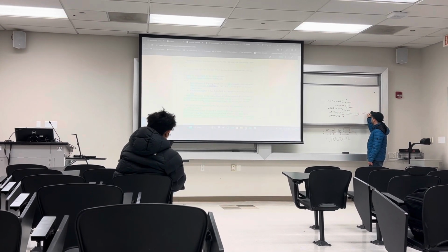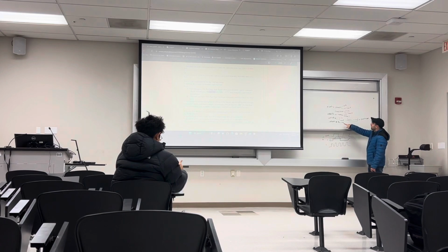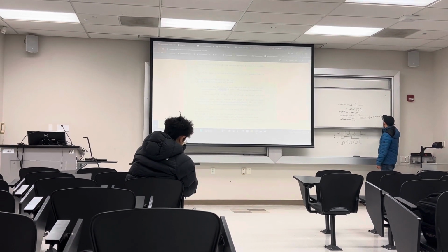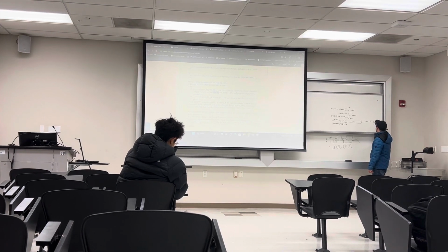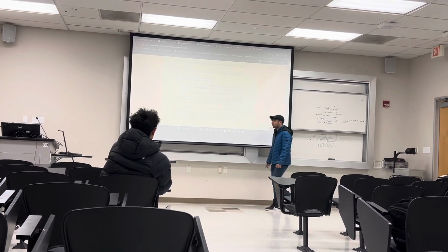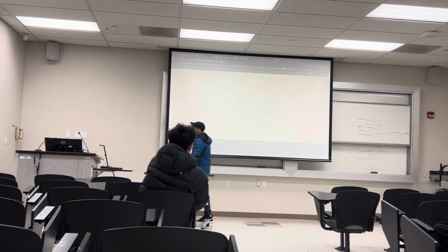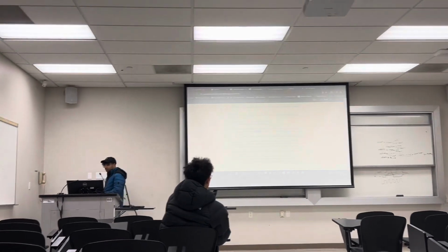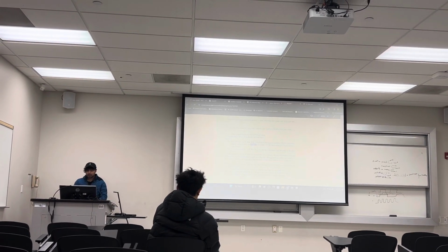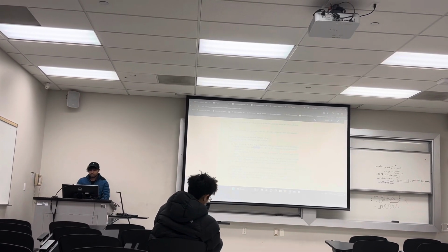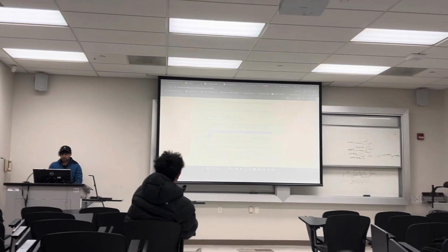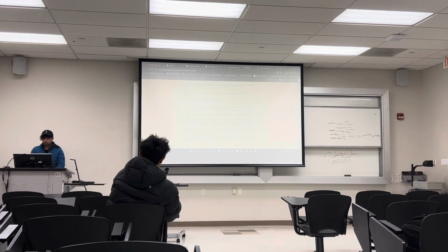So do the post layout of this one, and then again on this test bench, see the results, see the waveforms. So you need to show me the results of the first layout and also the post layout, two outputs. Okay, after you design the JK flip-flop, the next part is to design the up and down counter by using these cascaded JK flip-flops.